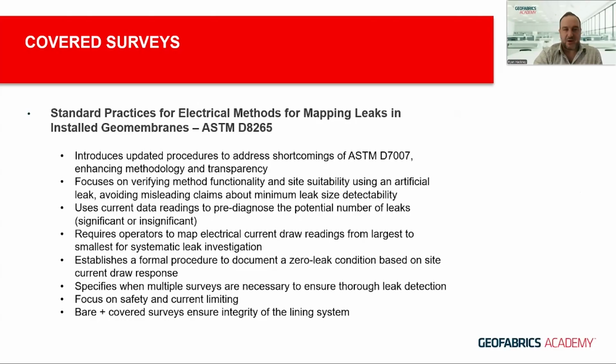I think the takeaway from looking at both bare and covered methodologies is that it's the combination of both of those that really ensures the integrity of the lining system. You would install a geomembrane and perform a bare survey, and that would pick up those smaller types of defects that we saw in the table, where there's a large proportion of defects that are caused by stones.